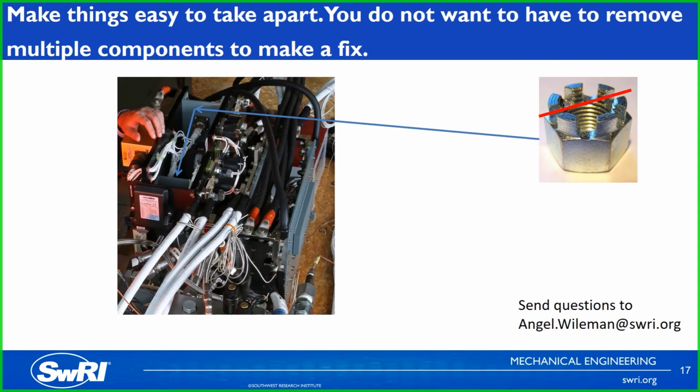But not only did we have these castle nuts, they were hidden between two plates that were only about 4 or 5 inches apart. We put it all together just like we had it in the drawing the first time, and then after a day or two of commissioning, we realized that we had to take it apart to check a couple of electrical wires. Removing those pins and then those castle nuts became an issue that probably added a day's worth of work that was not necessary had we thought through a little better how we might take these apart.